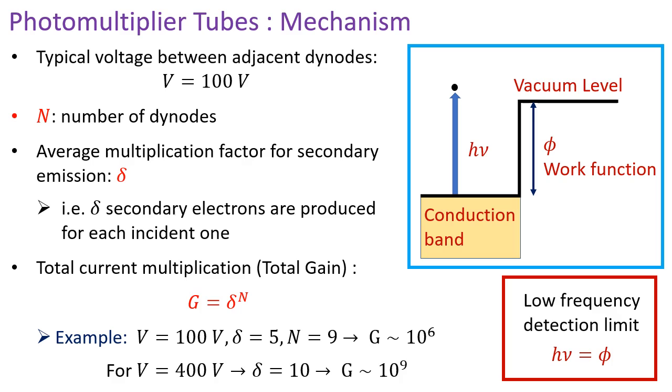Within that time, essentially the detector is not operational, so that is kind of a dead time. So you see that if I demand more sensitivity, then I would have to compromise on the dead time because I require more time for the avalanche to build up, and vice versa. If I have more input, and I demand less sensitivity, I can probably quench the gain.